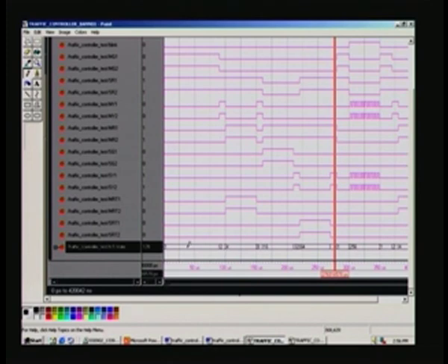So this corresponds to S0, S1, S2, exactly the same thing which we have just now examined in the simplified results, right. So that was the assignment made by the optimization tool, and because it is after back annotation, that gets reflected here, whereas merely after simulation, that would not have got reflected, right. So this clarifies that, and we have one more waveform which will also prove to you that it is indeed after back annotation, especially the gate delay you can see.